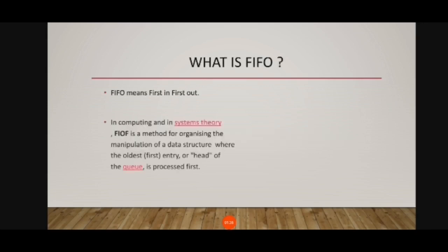Now what is a FIFO? Let us see. In every item of digital equipment, there is exchange of data between printed circuit boards, that is PCB. Intermediate storage or buffering is always necessary when data arrives at the receiving PCB at a high rate or in batches, but is processed slowly or irregularly. A FIFO is a special type of buffer.